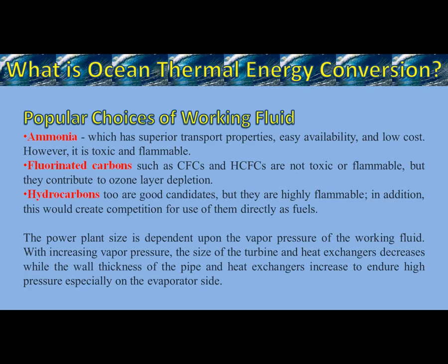About working fluid, these are the popular choices. First is ammonia, which is commonly used as a working fluid. It has superior transport properties, easy availability, and low cost. However, it is toxic and flammable.